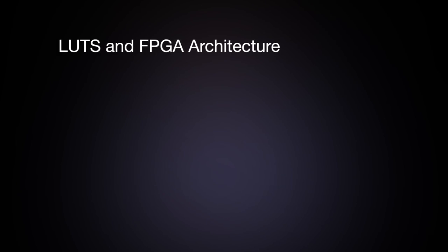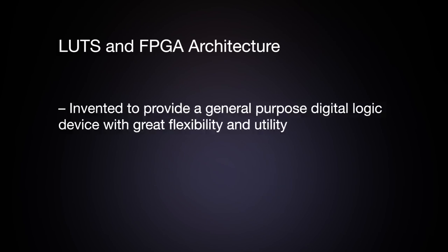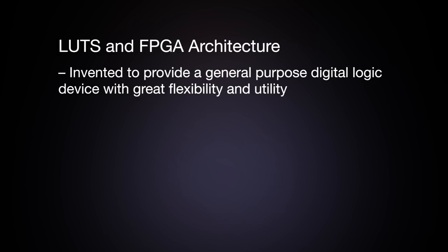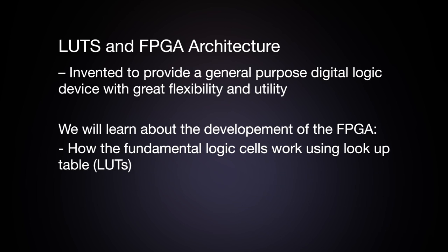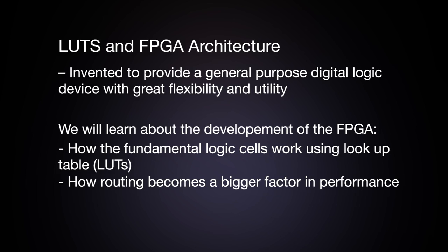Now let's look at LUTs and FPGA architecture. The Field Programmable Gate Array, or FPGA, was invented to provide a general-purpose digital logic device with great flexibility and utility. It has succeeded beyond the inventor's greatest dreams. Here we will learn about the development of the FPGA, how the fundamental logic cells work using lookup tables, or LUTs, and how routing becomes a bigger factor in performance.